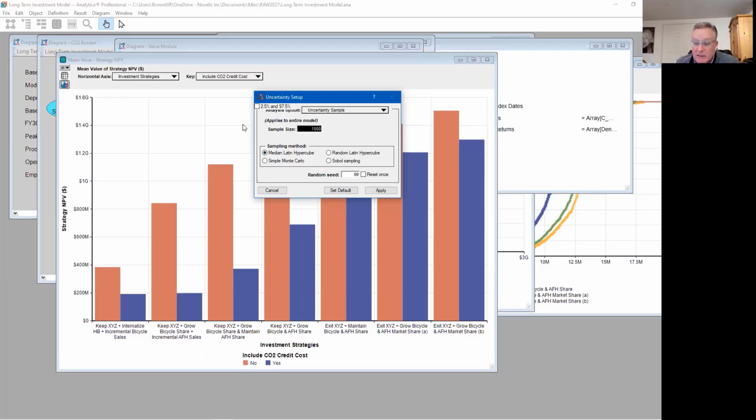It's a lot less noisy than, I would say, typical simple Monte Carlo. And what I mean by noisy is that if you take a Monte Carlo simulation, run it at, say, 1,000 samples or trials, calculate the mean value of your objective function, and then rerun that same simulation using a different seed but the same number of trials, the mean value or the expected value will not necessarily conform very closely in many cases, depending on the level of nonlinear effects you may have in your model.